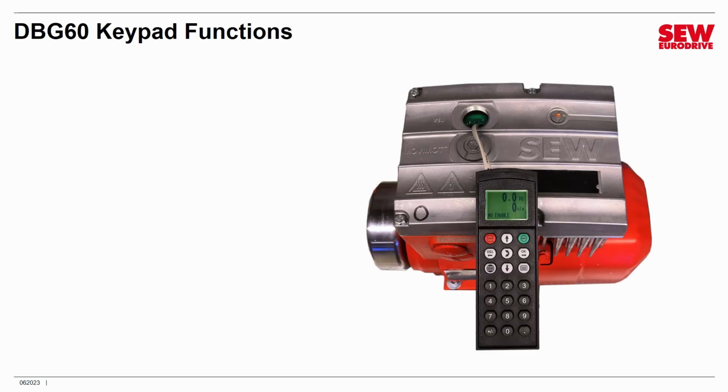What does the keypad do besides displaying errors? It actually does quite a few things. First of all, you can use it to monitor the MOVIMOT state, and in the picture here you see a keypad being used for that purpose. Of course, you wouldn't do this in an operating environment, but you might do it during setup when you just want to confirm that everything is operating correctly. You can see, for example, that the keypad is telling us that the drive isn't enabled yet, and that's confirmed by the fact that the indicator light right above it is yellow. It's also telling us that the output frequency is 0 Hz, which certainly makes sense if the motor isn't running, and it says that it isn't drawing any current out of its total possible current that it can draw.